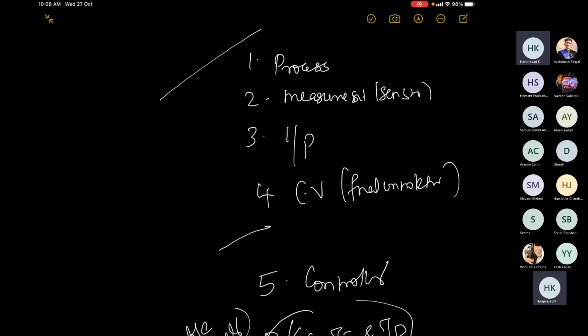So you went ahead and checked the stability, drawn the overall closed-loop transfer function, fixed the poles, did Routh analysis or even drawn the root locus, and you got a clear understanding: if my poles go this side, this is the boundary in which you need to work. Done. Then as a first cut, you started operating the plant. At least it is stable. Performance you look at later. Now, you were asked to make a product concentration of 98% purity.